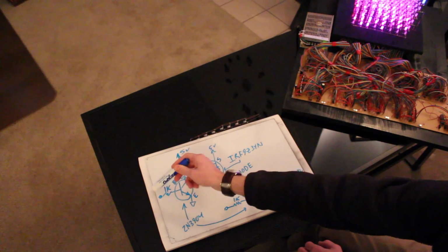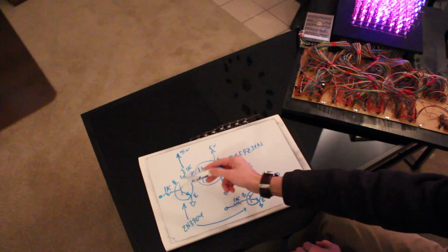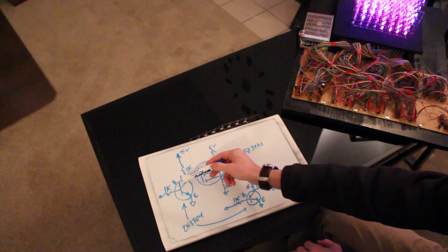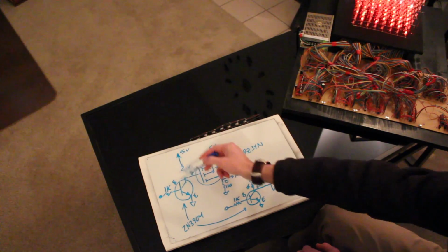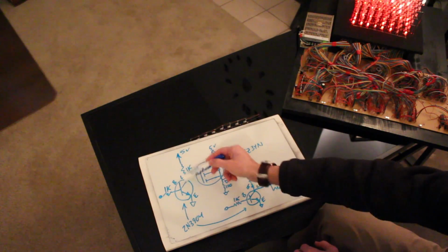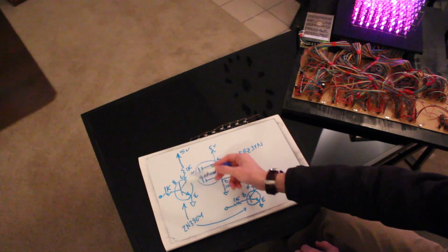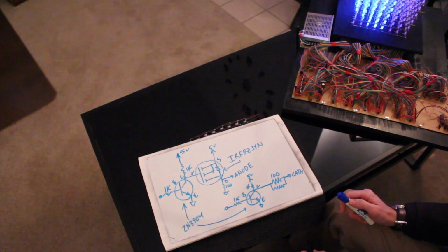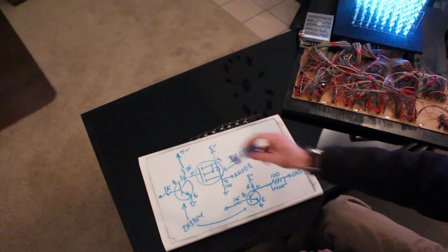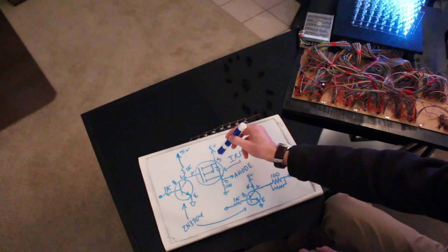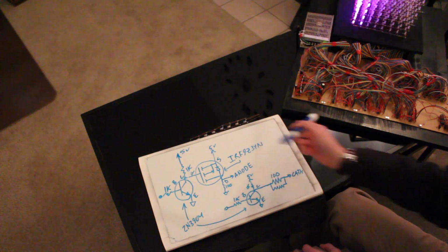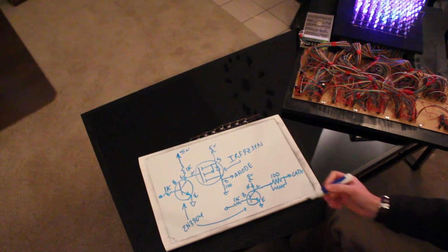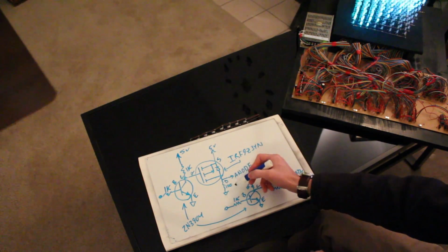As soon as I make this pin here high, it saturates this transistor and it moves the state of the gate pin from a high, because it was getting pulled up here, to a low, because this just becomes like a switch and it pulls it low through the emitter. And then it turns the P-channel MOSFET on. We get 5 volts through the source to the drain, out to the anode. And then you're asking yourself, what about this 100 ohm resistor here?